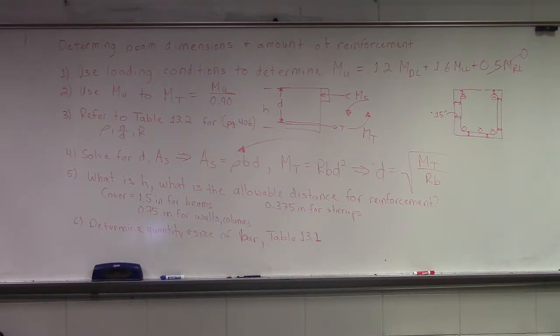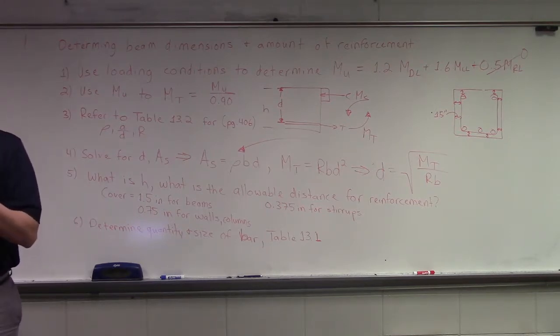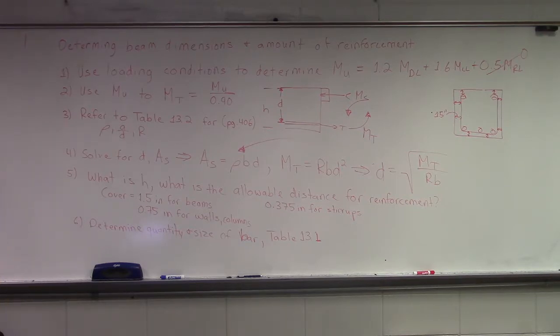So remember that you have to go back to the code and see what size aggregate you are using, because you can't have smaller openings than the aggregate that you're using. Typically speaking, the design criteria is separated by either the width of the bar, the diameter of the bar, or 1 inch spacing, whichever is greater. So if you're using a 3/4 inch bar, you can go to 1 inch spacing, and if you're using a 2 inch bar, you can go to 2 inch spacing.